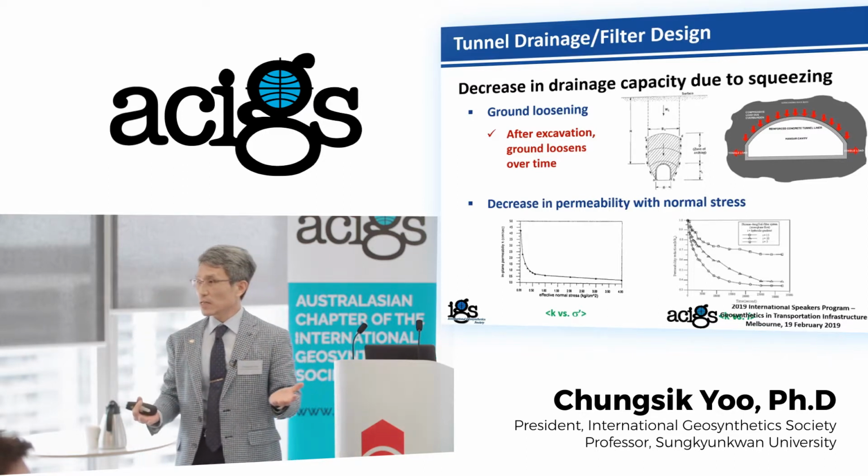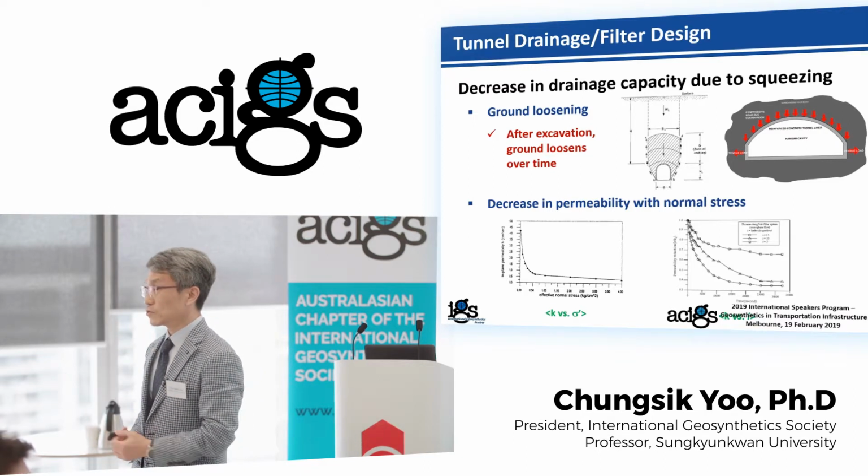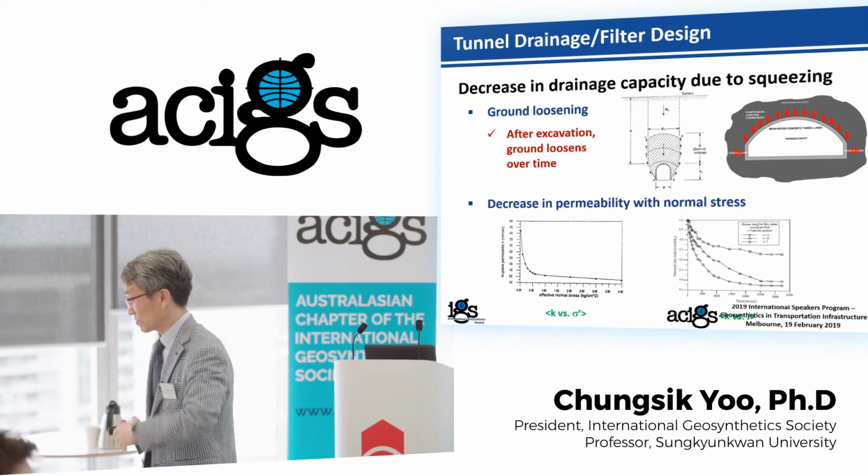For the squeezing, we cannot do anything because that's a natural process. So what you have to do is use thicker geosynthetics. The thicker, the better.